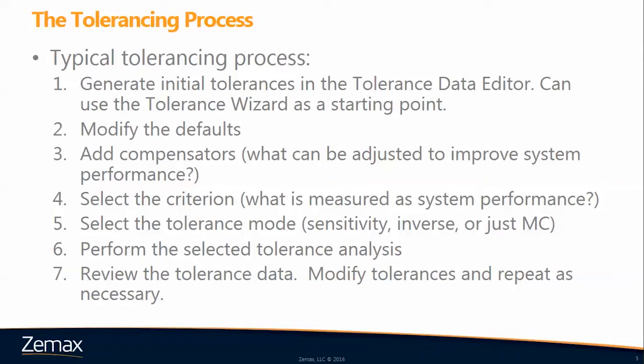After that, you perform the selected tolerance analysis, and this could take quite a while. And then in the last step, you review your tolerance data and then repeat as necessary. You should expect to repeat this process over and over again as your design matures.